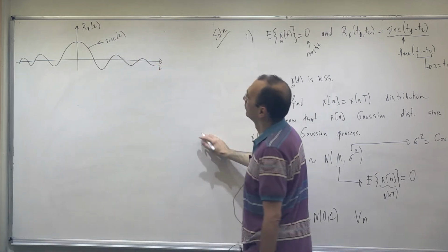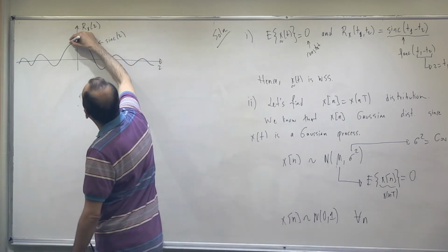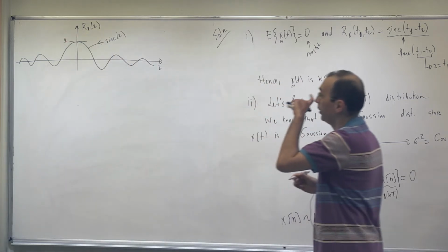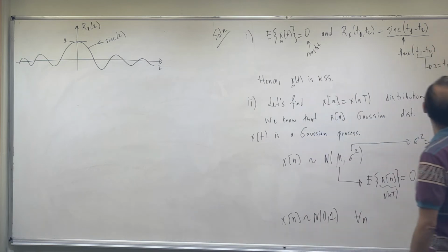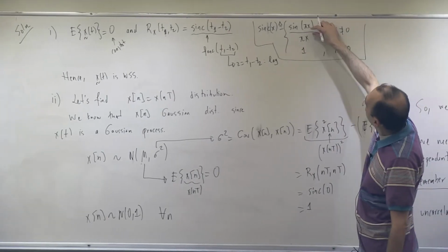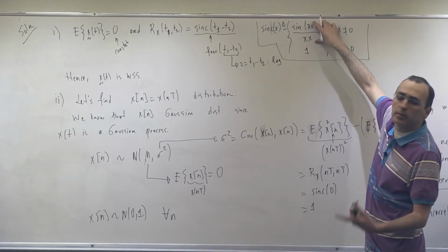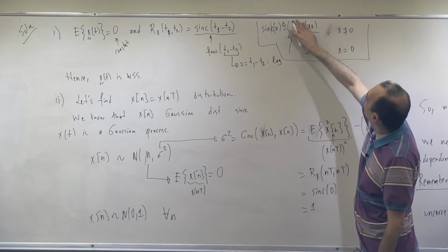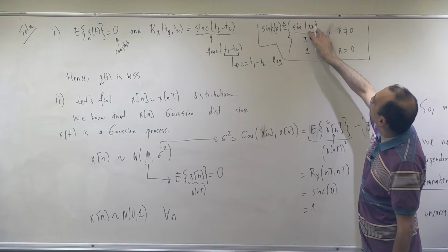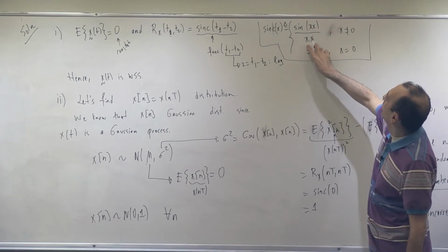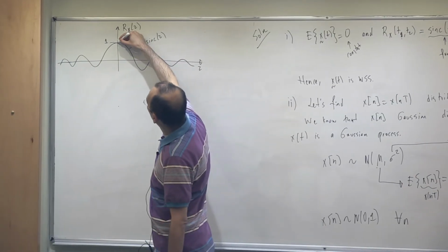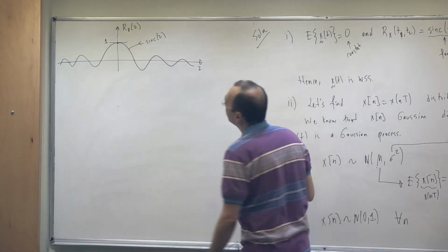As we have said, this takes the value of 1 over here. And if you evaluate this sinc function for small x values, as x goes to 0, by L'Hopital's rule, you get 1 also. Or you can approximate the sinc function with small argument as the argument itself, so the argument divided by itself, you get 1. So no surprises, this function approaches 1, and the value at 0 is also defined as 1.